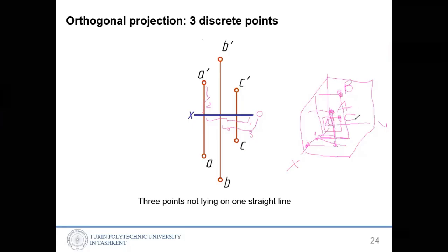So point C is here. So in the space, if the capital A, B and C points are given, that is in the 3D space. In the 2D space, or orthographic projection, it will be something like this. On the top of OX, A dash, B dash, and C dash are given, and in the bottom, small a, b, c. So it's given, and in between there will be a line. It might be a continuous line or a dash line.